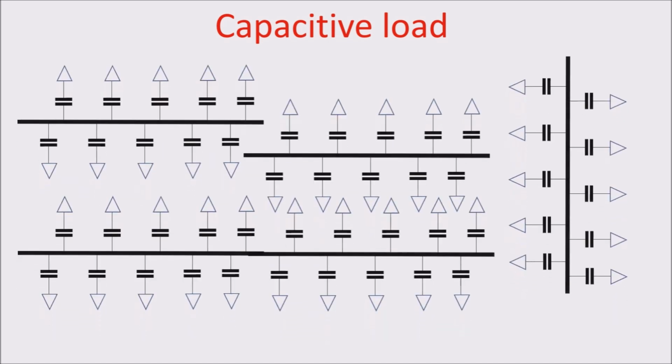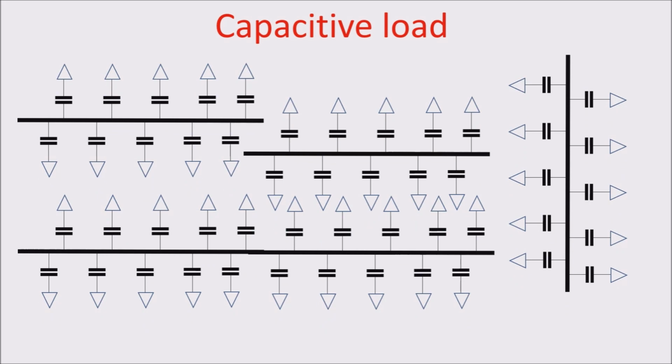Let's see every factor one by one. We start with our little but decisive capacitance. We have to imagine the CPU as a grid of metal lines which lead thousands of capacitive loads. This capacitance comes from the MOSFET gates, but also from any parasitic capacitance in the circuit.